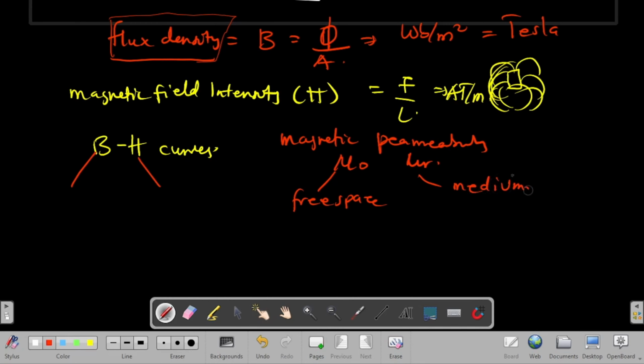So depending on the medium, you have the magnetic permeability. The idea is that if a magnetic effect is being generated by our force, the magnetomotive force, every material would allow a level of permeability, so the quantity of magnetic flux that will be flowing may be influenced by the material property. Using iron, steel, or bronze, they will all have different inherent properties that will affect the flow of flux.